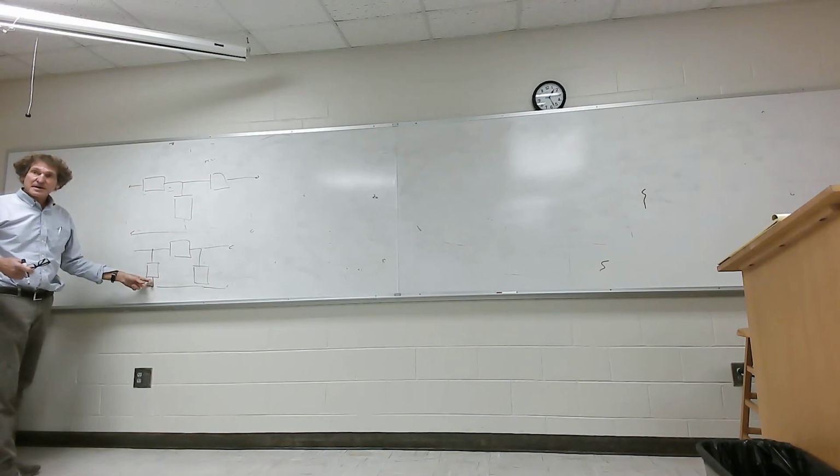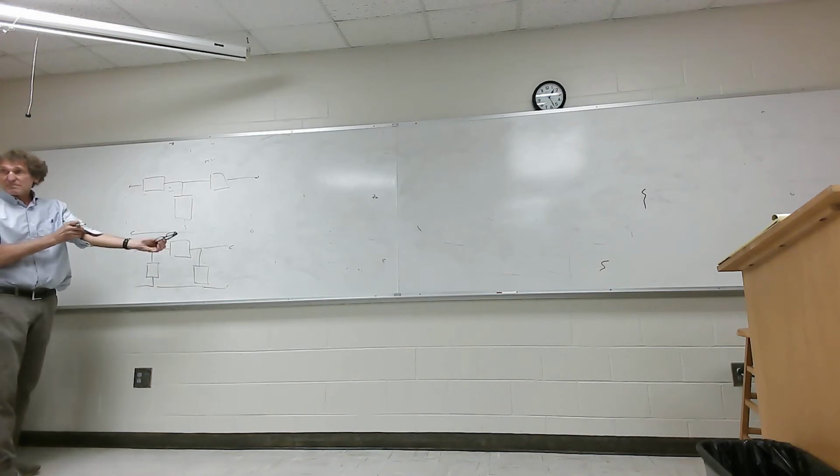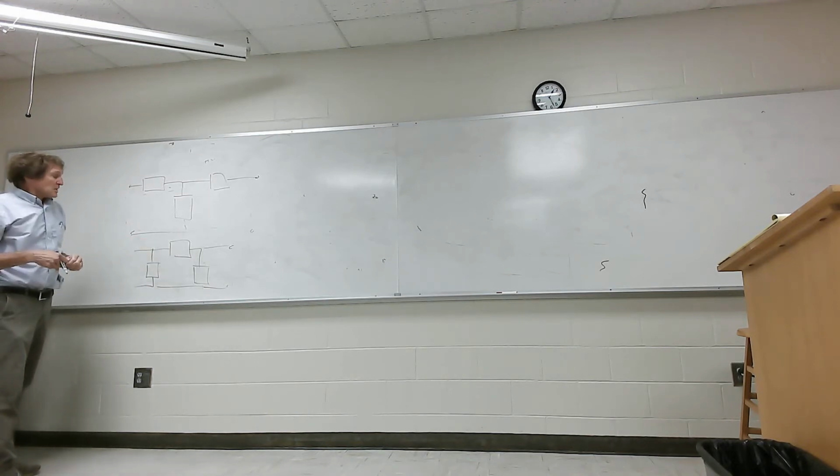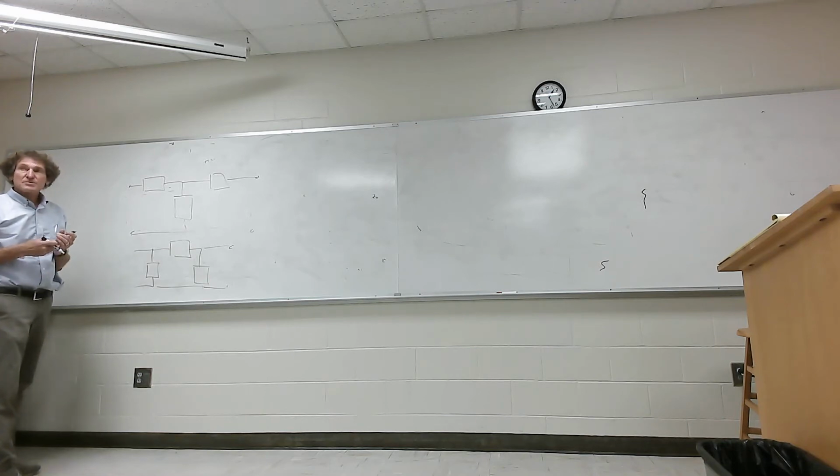This is a bad design, remember that, because the inductor's in parallel with whatever you're feeding. And that means no DC biasing possible. So those are the 2 types of configurations for band pass filters.